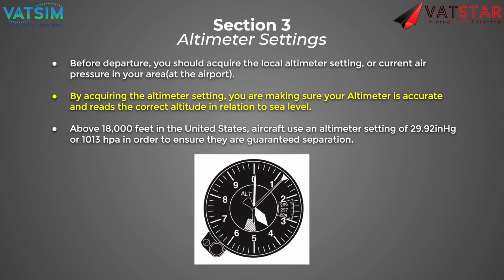The airport elevation. Yes, exactly. If you can't get your altimeter setting, just set it to your field elevation. And you'll notice there's this little window here, and this is how you set your altimeter setting. Right now there's no arrow here, so you can't actually set this. But this is your altimeter setting in inches of mercury. So this is 29.60 inches of mercury, this dash line here. This is 29.70, 29.80. But if you set this to your field elevation, you'll have a pretty good gauge of what the actual atmospheric pressure is for your location.